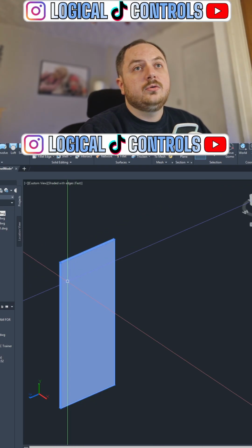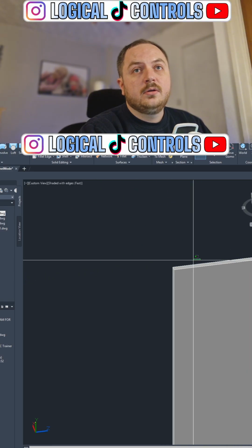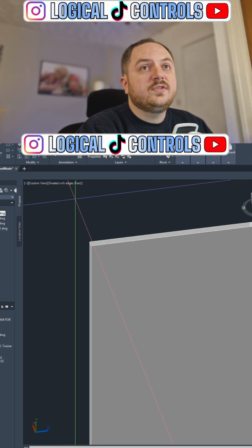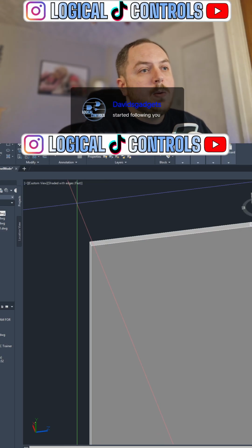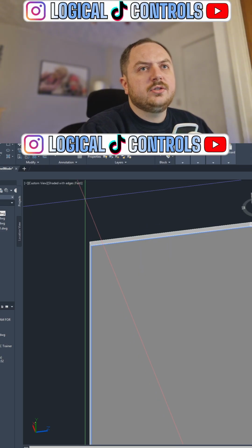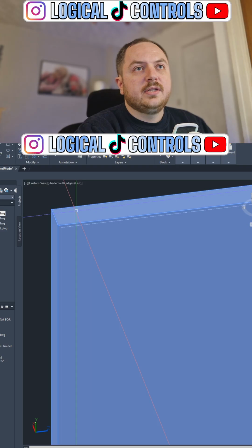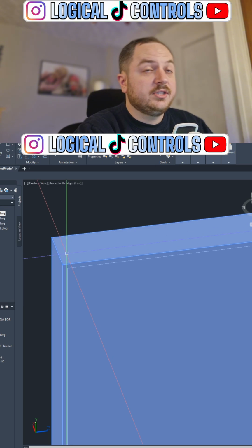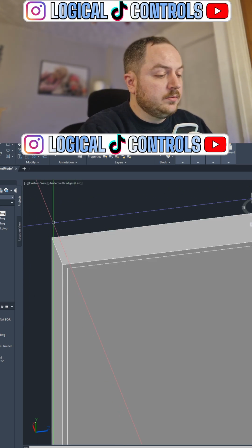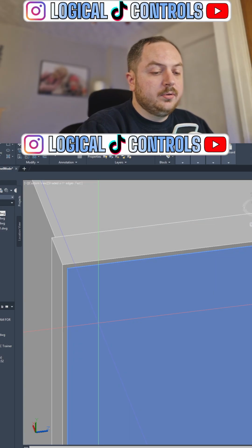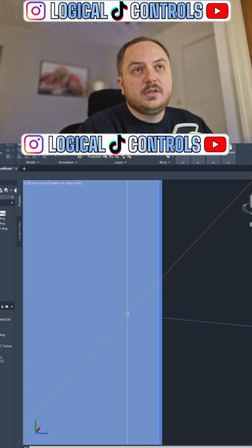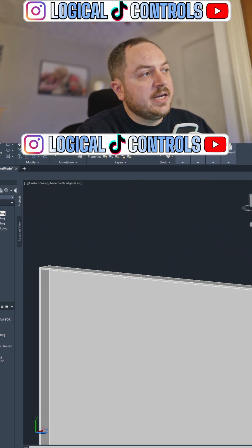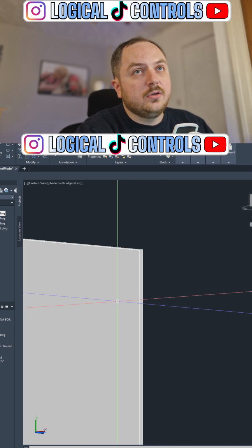Right, so that's now a hollow shell of a door, I believe. We're going to turn it back round and try and grab onto our rectangle. I'm going to offset that by, let's say, just 2mm. So now you can see I've got a solid mass, which is actually hollow now. Then I've got a little rectangle here. I'm going to press pull and press that in by 5mm. Did that work? It didn't. My shell, oh no, it did work. There we go. So you can see now I've got what's starting to look like a door.